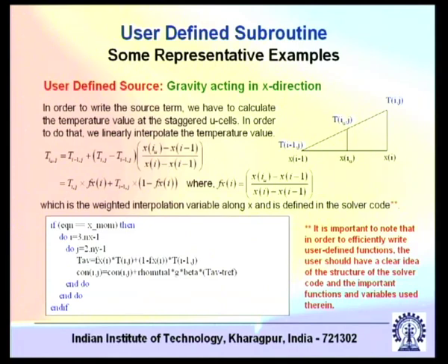So just recall from your basic understanding of natural convection that if you use a Boussinesq approximation, then you can write the variation of density in terms of the variation of temperature, and that is expressed in terms of a volumetric expansion coefficient. So it will come out to be rho g beta into T minus T reference or T minus T infinity, depending on whether it's an enclosure or it's a problem with an atmospheric boundary layer.